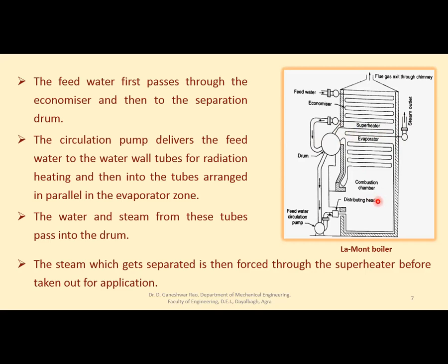And what about these gases? The gases have given their energy in this radiating evaporator, then in the superheater, then in the economizer, and finally they will leave through this chimney, right? So this is the working of Lamont boiler.